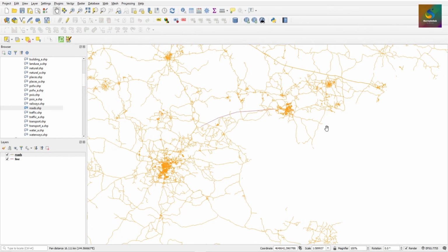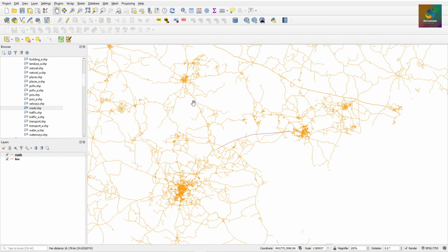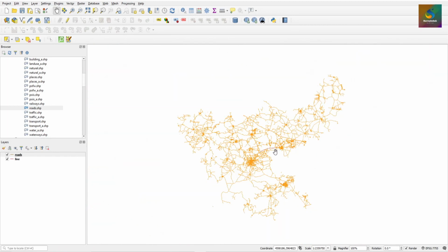What is on the fly? On the fly means 4326 projection converts itself to 7755 with the inner reprojection system. So it converts on the fly to this projection and sets at the exact location where it was. So this is all about the projection.